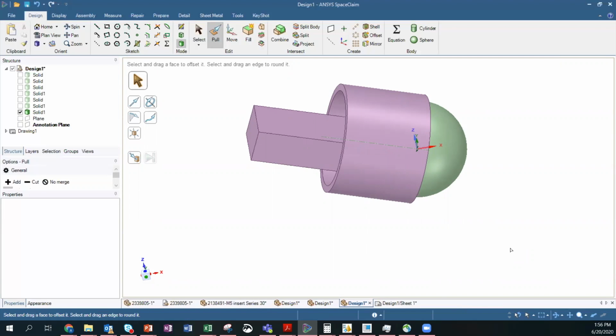And one of the good things is, say you're going to put a camera outside, like in Arizona, or in the desert in Utah mountains, where the temperature is always above 100 outside, then it has to withstand a lot of heat. Then nylon is the best. But if it's the home and it's hardly exposed to high temperatures, then PBT is good enough. So that's how we choose the material. I think in your case, it's going to be home. So you can stick with PBT.